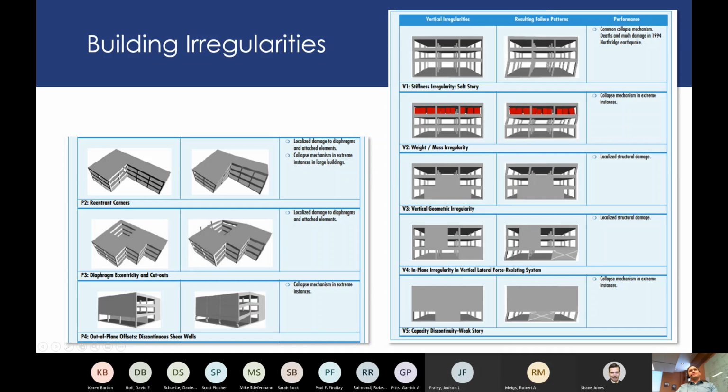If you have two wings of a building, that intersection point is another design obstacle. Diaphragms, if you have holes in your diaphragm. I mentioned before how diaphragms help distribute your lateral loads to different frames and bays. If you put a hole in it or cut a weird shape out of it, it's gonna result in more design. Also, with irregularities, depending on the type and the severity, we have to increase a redundancy factor, which is 30%. That's an additional 30% to the seismic loads. So again, we can design around these, and it's not that big of a deal, but it will save you, the owner, money in the long run if we can avoid those.